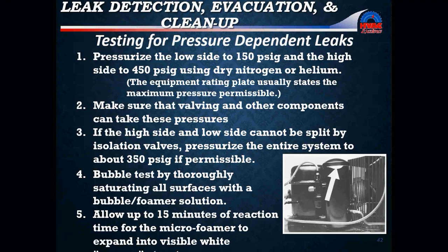Okay? Make sure that the valving and other components can take these pressures. If the high side and low side cannot be split by isolation valves, pressurize the entire system to about 350 psi. That's usually pretty good. Bubble test by thoroughly saturating all surfaces with your soap bubbles or foaming solution.